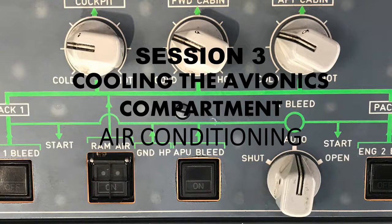Okay. And so when we have that closing of the isolation valve, then we're going to have air from the extract fan be able to be discharged outside the aircraft through the extract valve. So we have an extract valve too, and that's what, under those conditions, will have that go out.